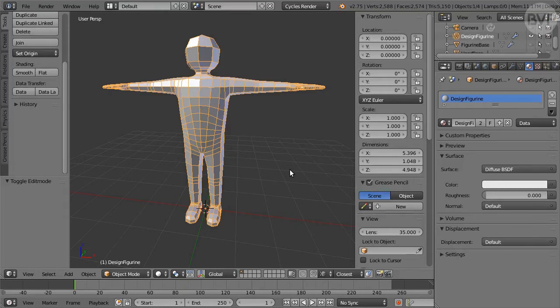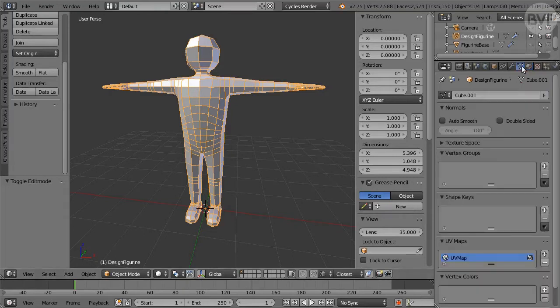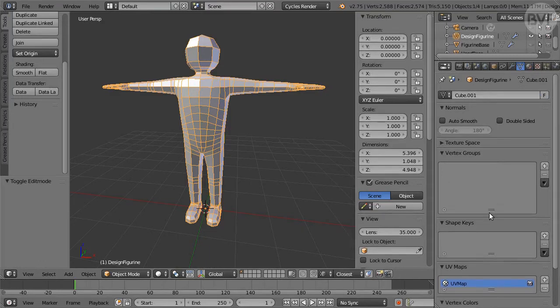For the armature to work, the mesh must have corresponding vertex groups set up. There are two ways to do this, the easy automated way and the better manual way. For best quality, we'll choose the manual approach. The work of manual vertex group weighting can be tedious, but we can partly automate the process. We take advantage of the fact that the mirror modifier can transfer vertex groups to the mirrored side, provided that correctly named groups already exist.